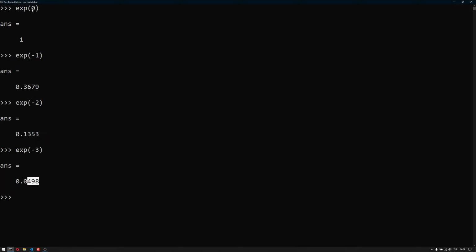So we are looking for, or we are aiming for, the time where this is basically 0.02, not 0.04, because we will have a 2% band and we will be happy with that. So if it's not wiggling more than 2%, then we say it's settled down, we don't have to wait further.